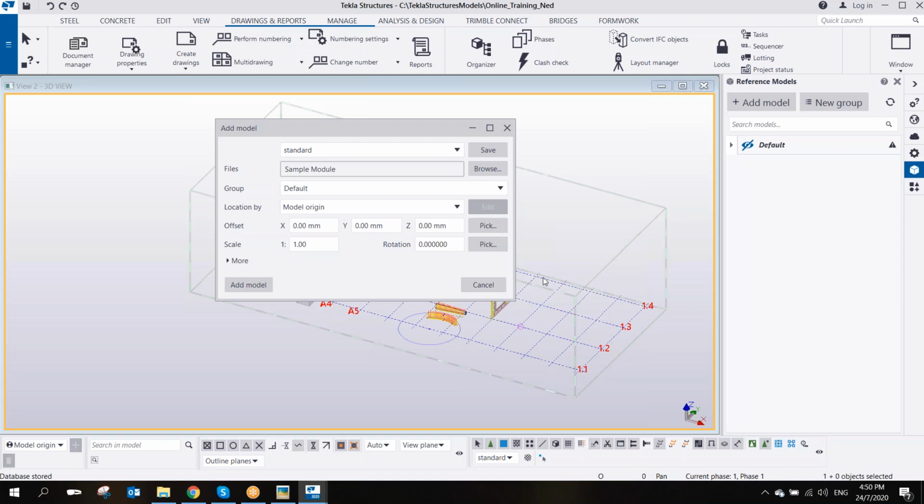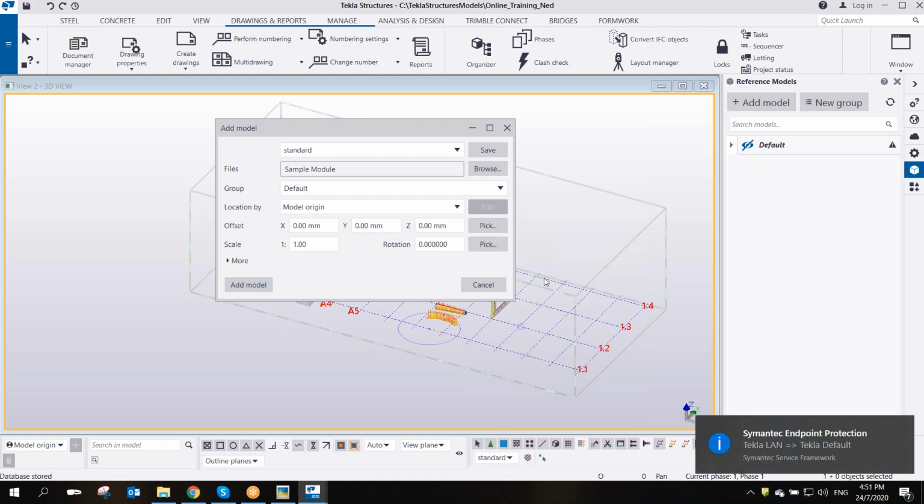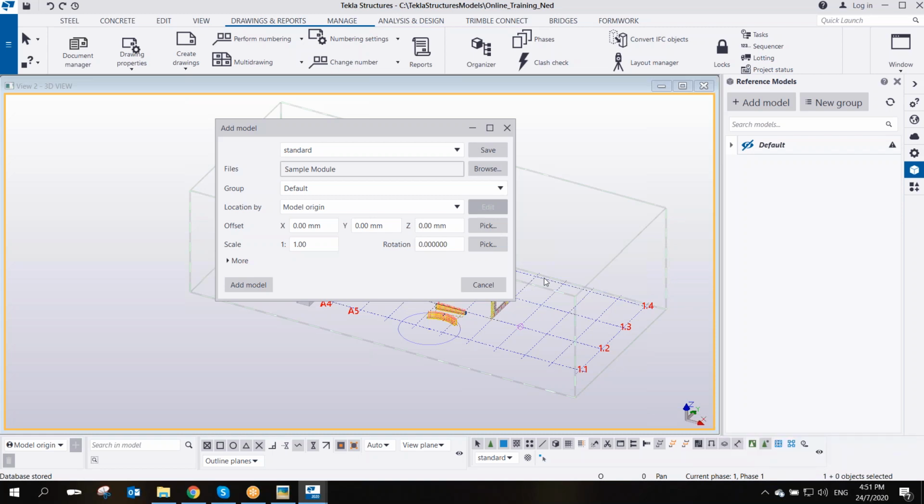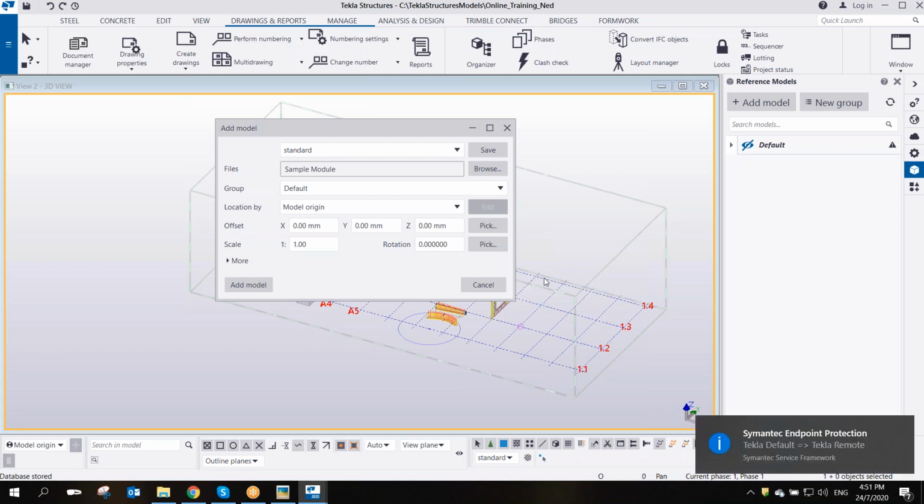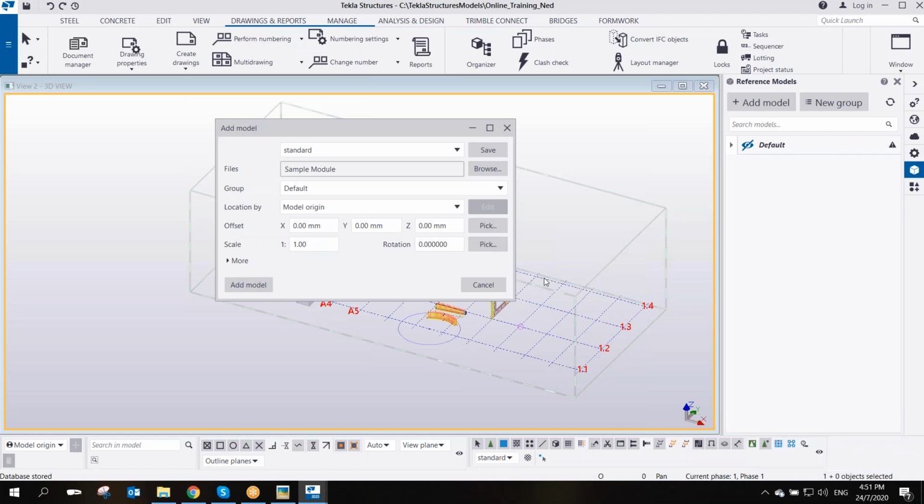Actually, it's the same in AutoCAD, because the Tekla Structures 000 and the AutoCAD coordinates 000 are the same. But in Revit, they have two different coordinates: the project point and the survey point. So what we need them to do before they export the IFC is set the project point. But in this case, I will just use whatever they have given to us.